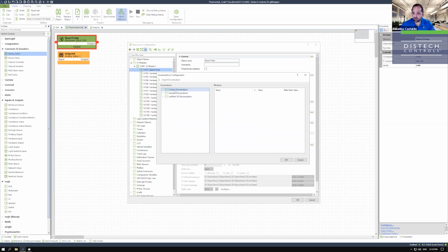So we talked earlier about importing a custom enumeration. You have some sort of special feature. You could add this enumeration, whatever you want to call it, and you'll add your members. So you could add a fixed value starting at 1, for example, for BACnet, or a range, anything from 1 to 5 or whatever, and you'll call it sequence 1 or whatever, and you can just keep adding your members that way.